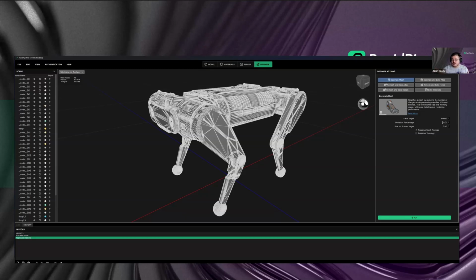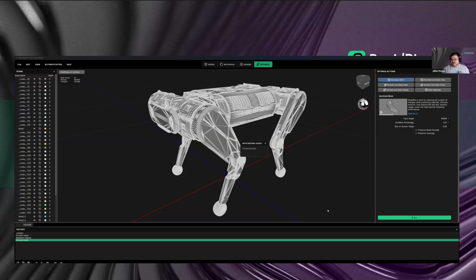And then you can top this with a cap. So you can say, hey, my face target is X and my deviation target is Y. If you decide this mesh would need 50 million resolution, please cut this off and give me 5 million instead, or 1 million, or in this case, 800K, and just let me deal with it basically. So if we just run it through, we get the output with the specified face count, in this case probably because the deviation percentage is set to 0.01%. So it's really staying, if possible, very close to the input surface, meaning the calculated optimal resolution for this file might be like 2 million faces or something. This is at least what I'm expecting right now. And that's why it will hit the face target of 800K.